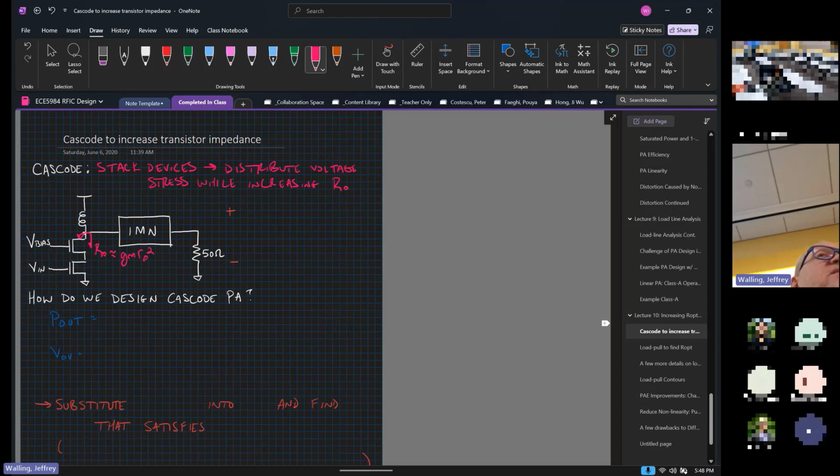Bear in mind, I am adding parasitics, and anytime I add parasitics, I might have to tune the parasitics a bit. So, more or less, the biggest problem here is I've got some parasitic capacitance that exists at this interstage node between the two devices, and that can reduce my gain because I have a path where signal at higher frequencies might want to leak through.